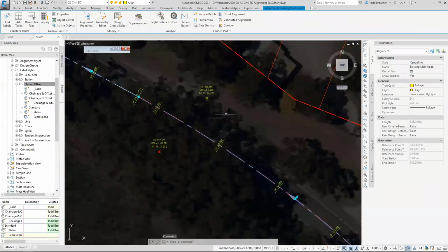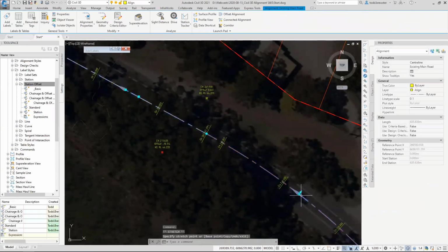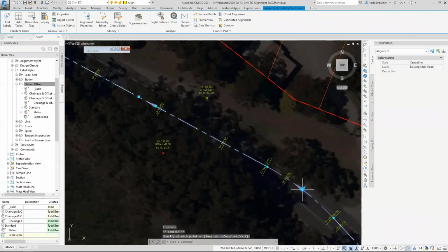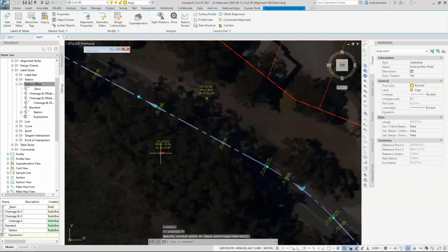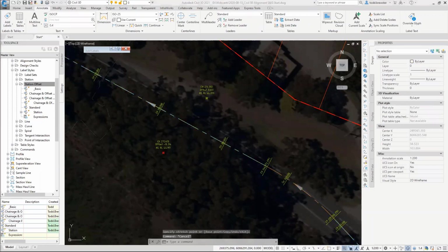And then to show you what happens if I change this alignment, let's go make it to that. That may be a bit more obvious. Let's go to that. We see how the red one actually shifts with the alignment because the chainage and the offset are maintained, whereas the other one stays where it was and those values change. It's the difference between fixed and station offset. All right, that's also an example of how you use your reference text.